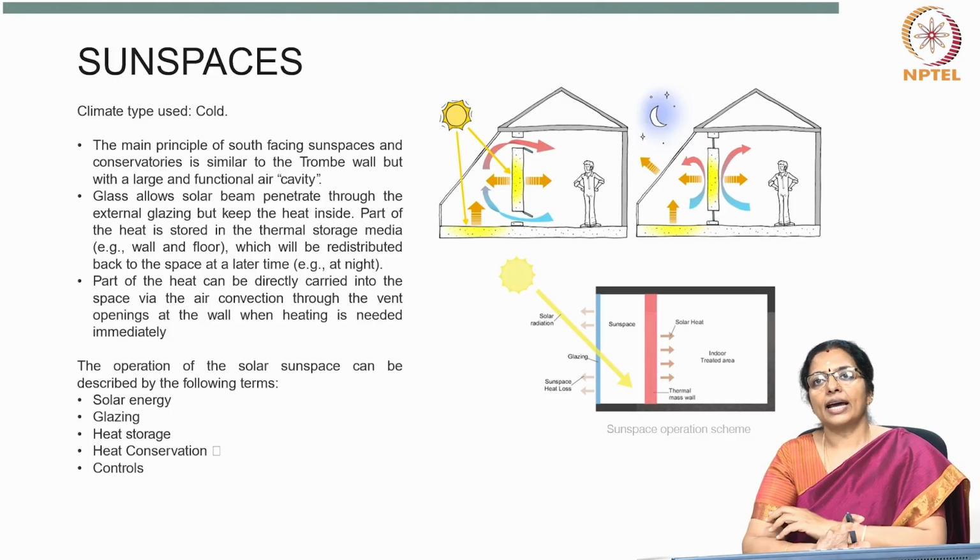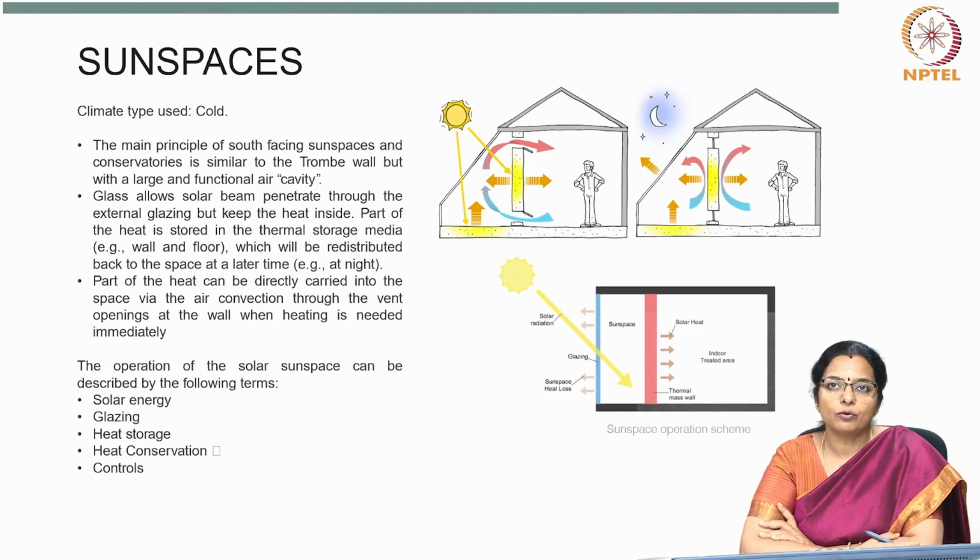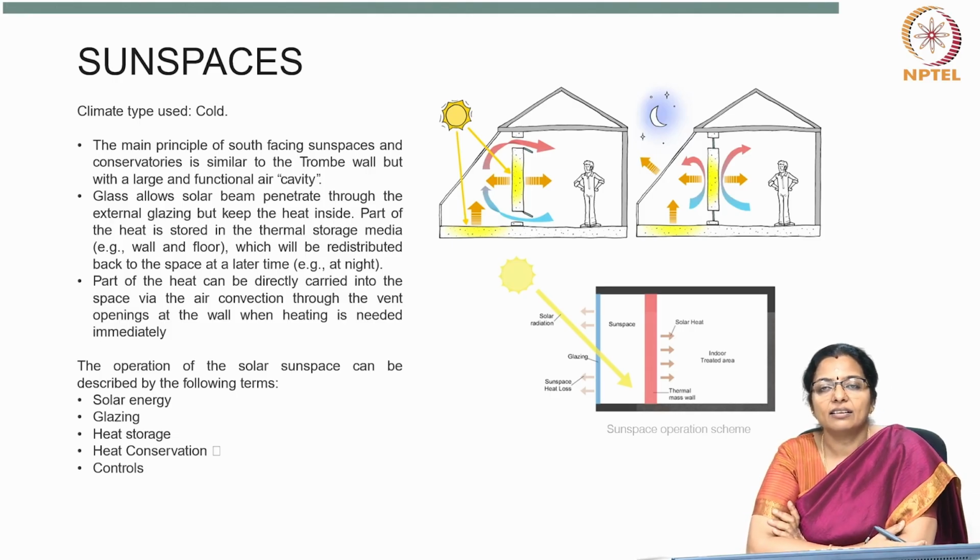The total direct solar radiation available for the sun space is deeply connected to the location of the sun space, the prevailing climate condition of that place, and the orientation of the window area. The effect of the glazing is that the glazing is responsible for the solar gains and the heat losses. Transmittance happens, which is the radiation that is neither reflected nor absorbed, that is called transmitted.